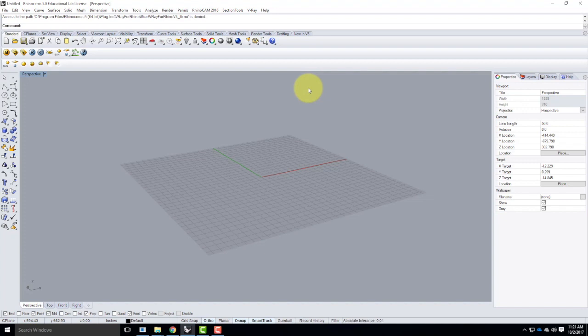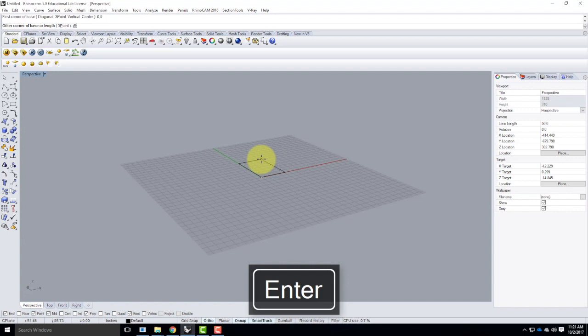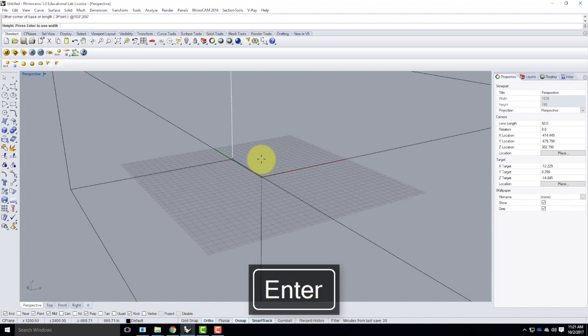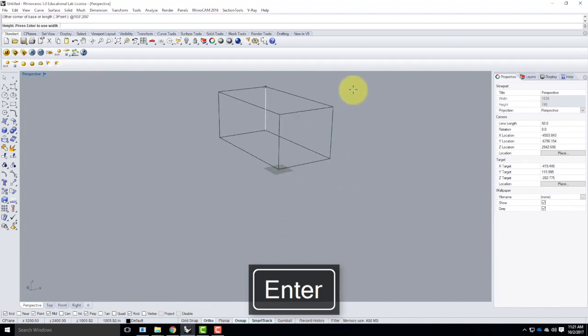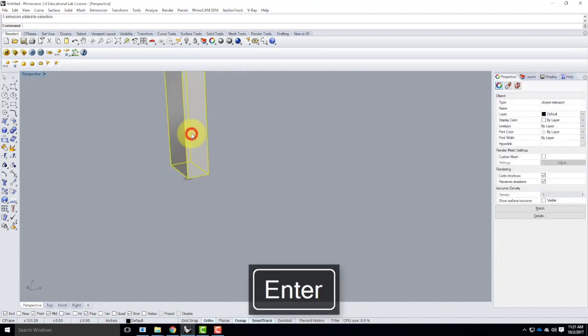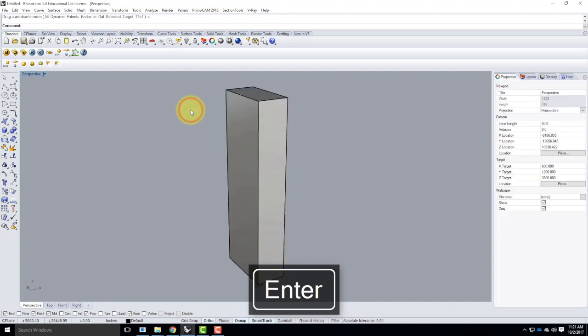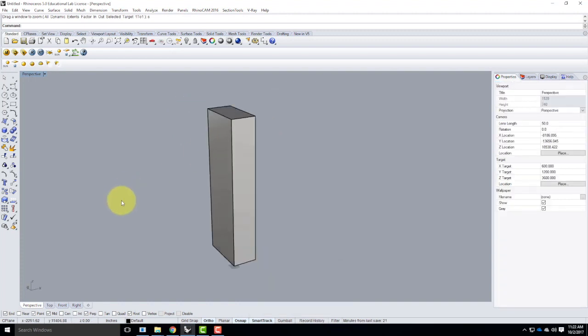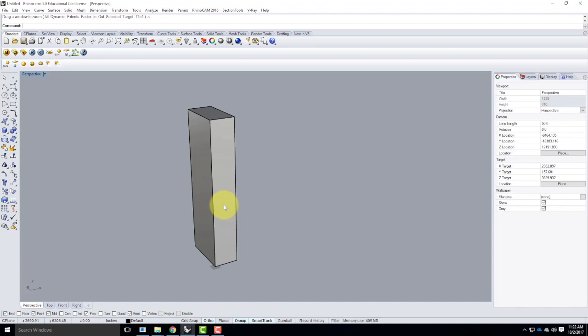So we can start with a basic, rectangular skyscraper. We could do a box corner to corner, for example. I'll do box corner to corner in this example. I'm going to start at 0,0. And our size here is going to be 100 feet by 200 feet as our base. And our height is going to be 600 feet, right? 600 feet, yep. And let me zoom selected, and that gives us a general sense for the size that we're going for. So this is its most basic form as a skyscraper. It also happens to be a rather boring form as a skyscraper.